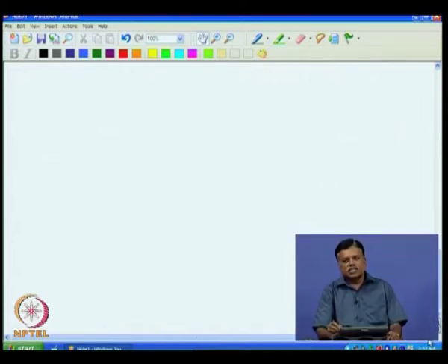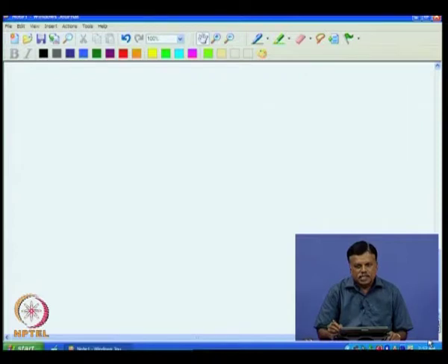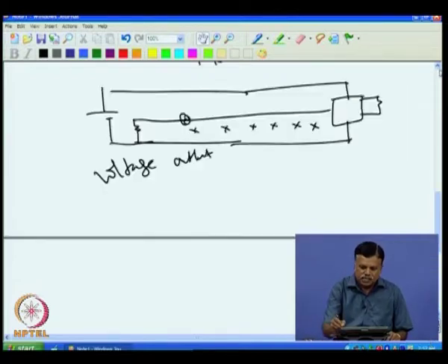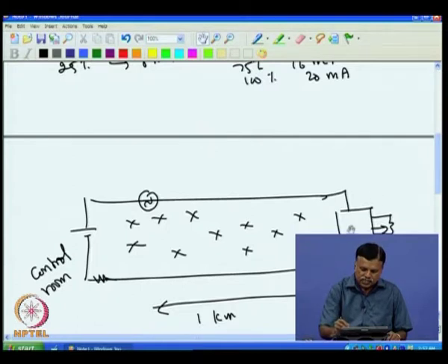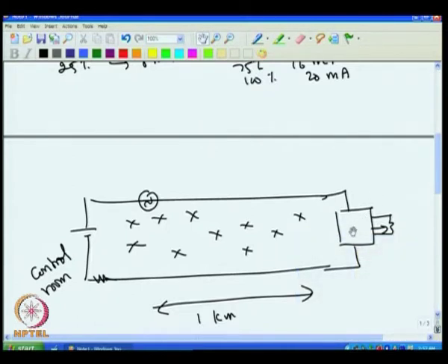Okay. So, this is the background of this 4-20 milliampere current transmitter. Let us see how to design the system, because as I said, this current transmitter we are designing here should send a current through this, the same current that comes and goes here, and that current should be independent of whatever the voltage across this, within the limit, and also independent of the noise induced voltage, and that should vary with this.